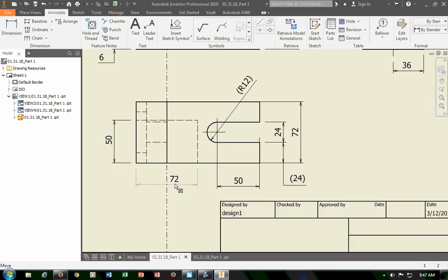So I'm going to drag these out. They snap to a standard position. I'm not quite sure. There we go. This guy, I got to pull the center lines out. Drop it to endpoints. You don't want dimensioning inside the part. It can get visually confusing.